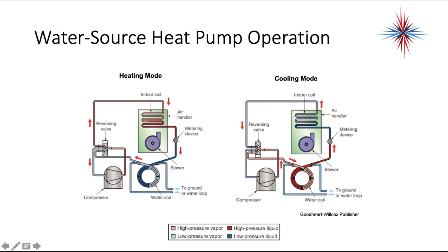In the cooling mode, I'm rejecting heat from that coil, which is now my condenser, and I'm giving it up to the water or ground loop.